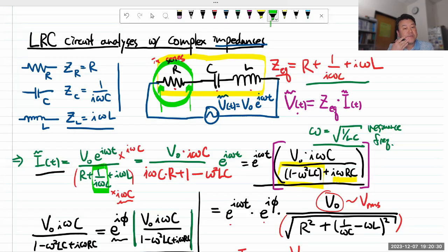So in terms of measuring things, you want the resistor to be reasonably large. However, when you think in terms of power dissipation, the resistor gives you what's called damping. It's what makes things oscillate not as well. And the amount of damping you have in an oscillator determines the sharpness of the resonance peak.